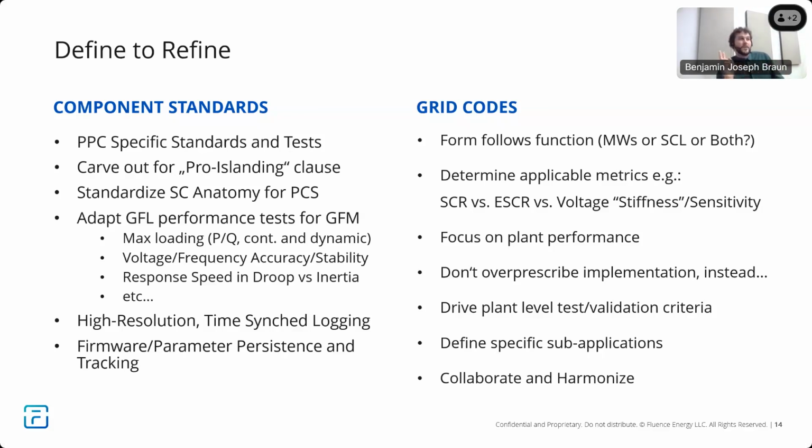We also see this loss of last synchronous generator test, which also gets at teasing out whether this is really grid forming or not. And NREL has put a lot of ink on paper about their impedance scans, showing the stability of the controller as well, and characterizing the response from grid forming versus grid following. I haven't seen anything exactly quantifying what limits would be passable and not, but maybe those are a couple of ideas. Hopefully it helps to answer the question.